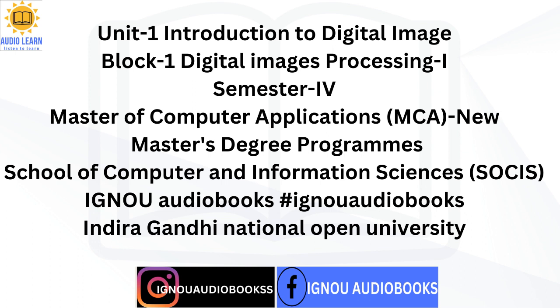The digital image processing is performed using digitizers, and this digitization process consists of 2 steps. One is called sampling and the other is called quantization. Sampling refers to considering the image only at a finite number of points. Each image sample is called a pixel, and quantization refers to the representation of the gray level value at the sampling point using finite number of bits. For example, 256 level quantization results in image storage of 8 bits per pixel.